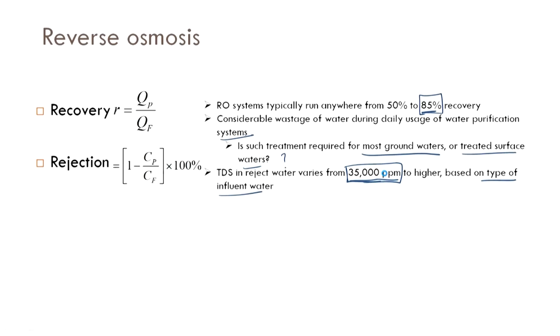But I guess the point I should have made here, which we did discuss earlier, was that groundwater, let us say if it is 400 or 450 ppm, and you know that there are no toxic compounds or carcinogens like arsenic and such, do you need RO? Not really, right. As we discussed, you just need pre-treatment to remove the suspended solids.